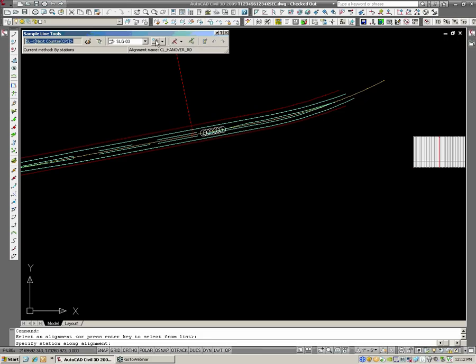The options, this stuff to the left, right through here on the screen, we really set everything up here already. We're right now at this step, this sample line creation method, and by default, when it first goes into this, it puts you in the at station chooser mode, and I don't really want to be specifying these by station.